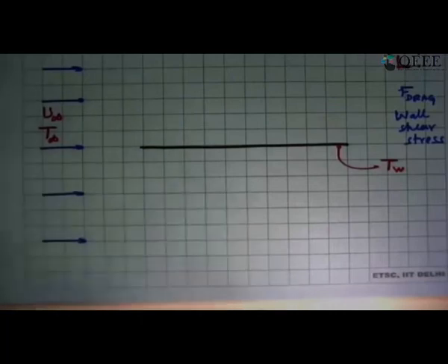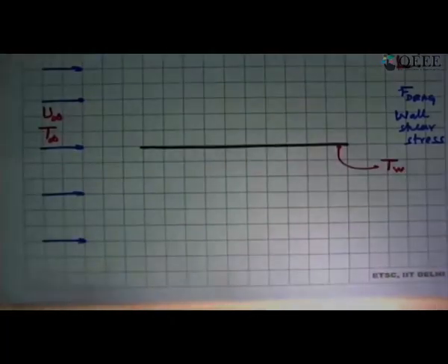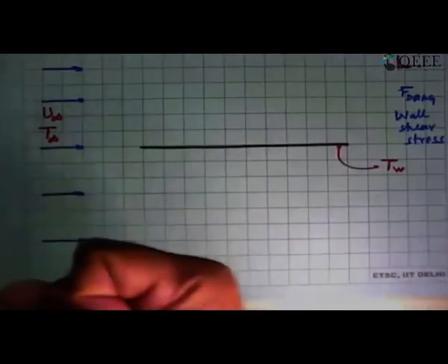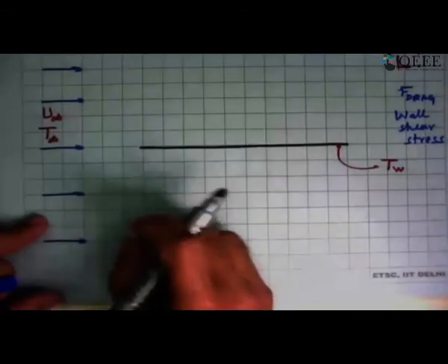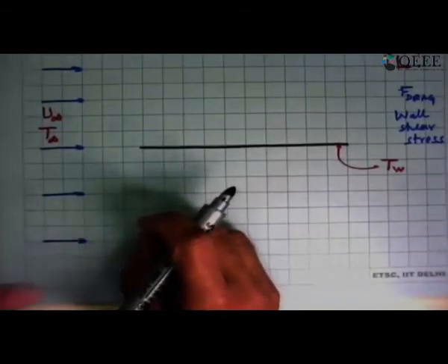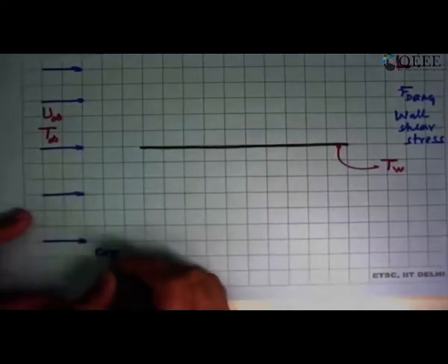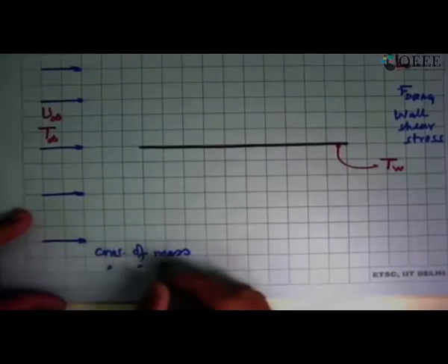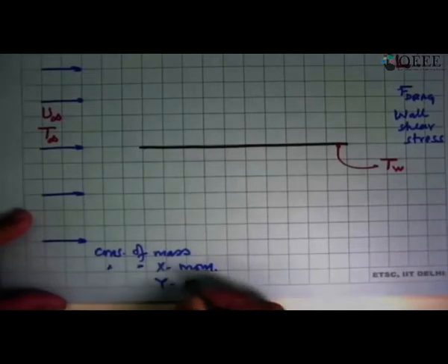That is what we are worried about in those cases. And we say, well, how can I calculate the force experienced by this plate? Which equation do I need to solve? Like in heat transfer, you can do an experiment. Take this plate, put it in a wind tunnel, put it on a load cell, measure the force. Fine, one gets the answer. What happens here is that I want to solve the equations, and we have learned that we have conservation of mass and conservation of, say, x momentum, and maybe conservation of y momentum.